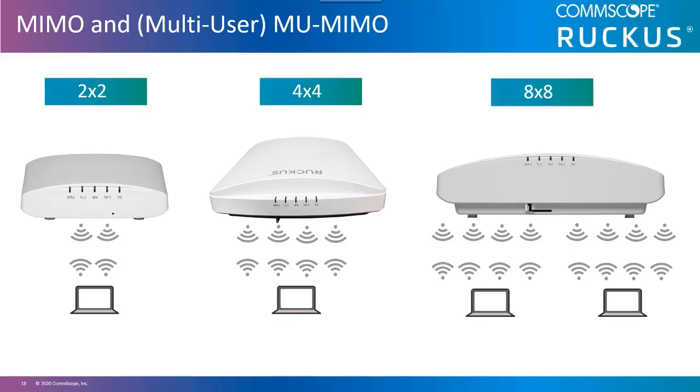When looking at AP capabilities, you will commonly see the number of antennas indicated as 2x2, 4x2, or even 8x8. This gives reference to the AP's capabilities and outlines data rates dependent upon which PHYs, modulation, and coding schemes are planned to be used. To optimize this, the client devices must support the same functionality.